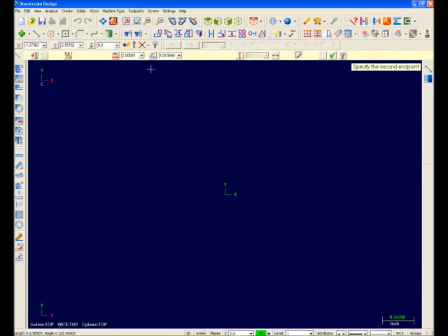Moving forward, this line needs to be 1.5 inches long, so I'll type 1.5 in the function ribbon bar and hit enter. I'm now locked into 1.5 inches for my length, so no matter how I stretch my line on the screen with my cursor, I can only create a line 1.5 inches long. So I'll use my auto cursor to find the horizontal position and click.